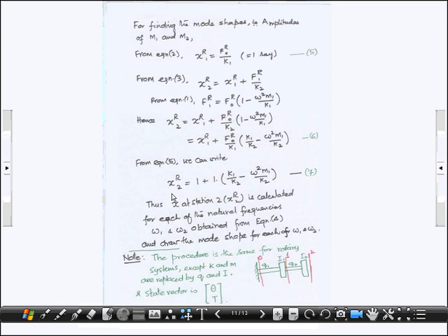Well, now we can look at the problem here. What we have taken is a spring mass system. We can handle the rotors with the shafts in the same fashion. The only difference is the state matrix is going to be theta, t instead of x and f. The rotary counterpart is theta and t, and in the place of K, the spring stiffness, you are going to get the torsional stiffness Q, and in the place of mass of the spring mass system, you are going to get the mass moment of inertia of the rotor. That is the only change.